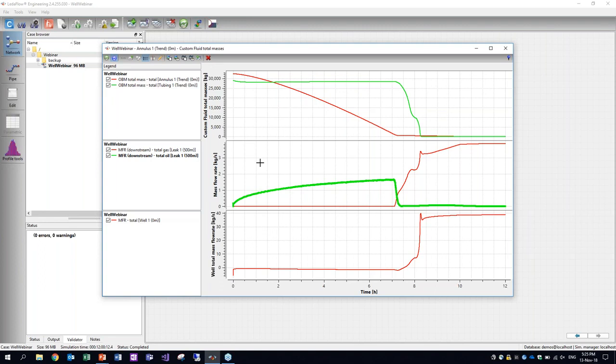So we're pushing all of this drilling mud that we have here, all of this gets pushed through the leak as oil here, and then after it's gone, we're taking over with gas. So it's actually not unusual for oil to go through a gas lift valve if you're doing a cleanup operation. Okay, Josh says oil is oil-based mud, so that's okay. It's showing as oil in this curve. Yeah, okay, that's good.